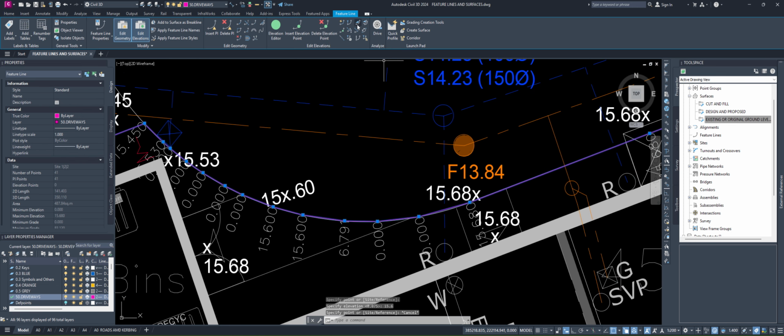Right. So this is the set grade 2. Like I explained, I'm gonna click on it. Now it's gonna let me select the first point. My first point is gonna be 15.680. Okay. It's asking me to specify elevation. Is that the elevation what I want? Yes, because we already apply elevation to that point.